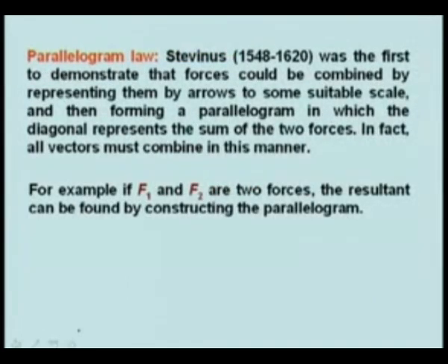Now we discuss the parallelogram law, which was given by Stevinus, 1548 to 1620. He was the first to demonstrate that forces could be combined by representing them by arrows to some suitable scale and then forming a parallelogram in which the diagonal represents the sum of the two forces.